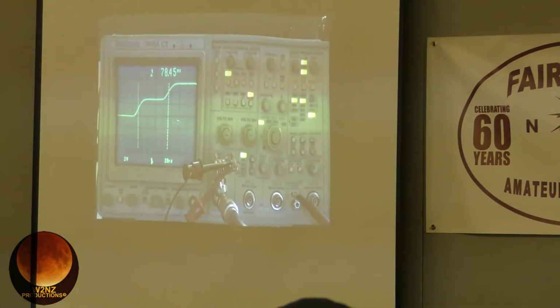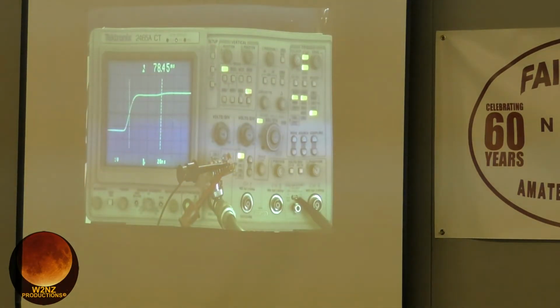Okay? Let's stick this thing on the end of the coax. Got to adjust it pretty right here, but let's adjust that. Oh, look at that. I can adjust that reflection up or down, right? If I go high impedance, then the reflection goes up. If the impedance that I terminate with is lower than the coax impedance, say I adjusted this to 30 ohms instead of 50, the amplitude is going to come down because the final resting impedance of this signal is going to be at 30 ohms, so I get a bigger voltage divider.